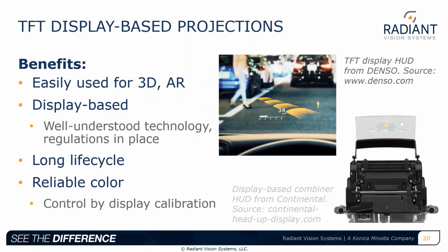TFTs are the most widely known technology for several reasons. One, they're the easiest to implement at this point in time, and the technology is widely available. We're seeing them used in traditional head-up displays, 3D, and augmented reality. The benefit of TFT display technology is that it's well understood, and there are several automotive regulations in place from a longevity perspective, which is something automotive applications always struggle with when introducing new technologies. Life cycle is crucial, and any display needs a life cycle of 7 to 10 years.